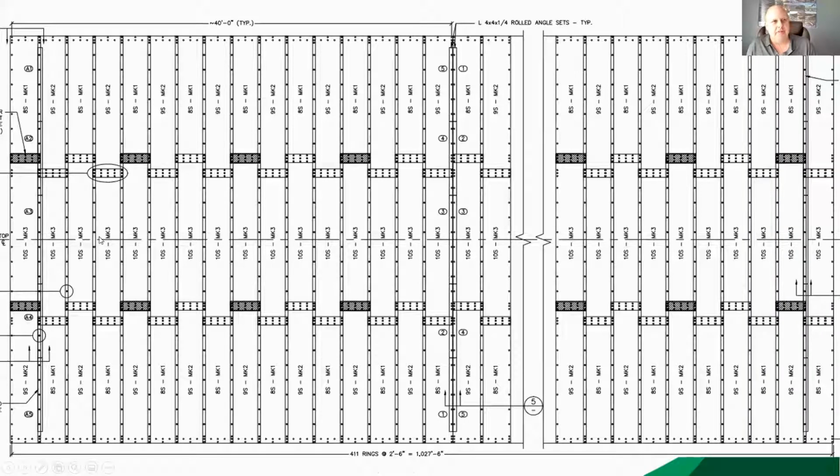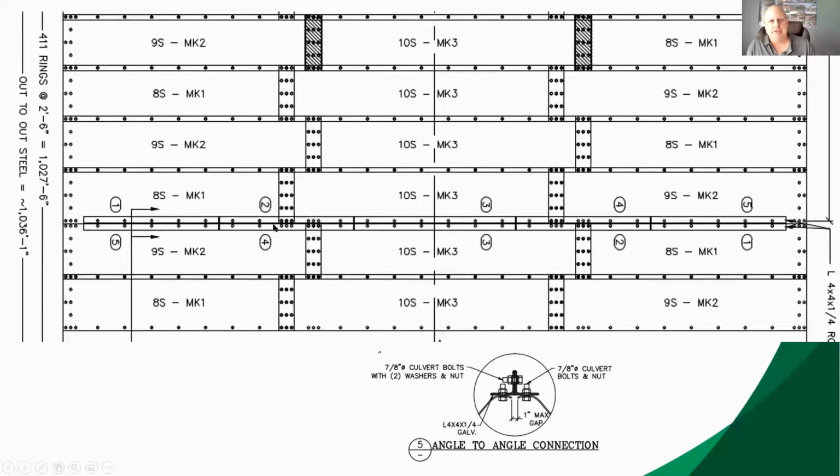Here's a plan view, a flattened view of the structure, as if you pushed down the plates and laid them flat. You can see there, this is a 40-foot section here. And then we're going to focus on this joint here. This is the joint between the modules. So these rings over here are all built up on top in a laydown area. These plates lap each other from ring to ring. At the place where this joint is here, the plates are basically butted up to each other.